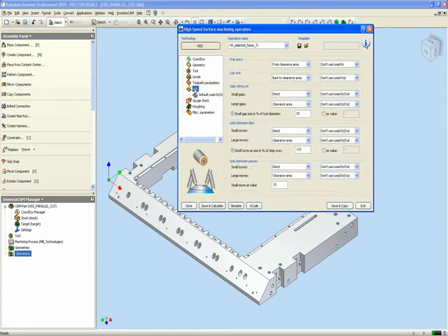Now let's go into our link area. Our link area shows us, first of all, how we want to approach our first entity from the clearance area, and whether we want to use our lead ins and, in the last exit when we leave the part, our lead outs. In this particular case, I'm going to use my lead ins, and I'll also use my lead outs in my last exit. As for what type of lead in and lead out we'll have, we'll show that to you in a moment. But first, let's talk about gaps along.